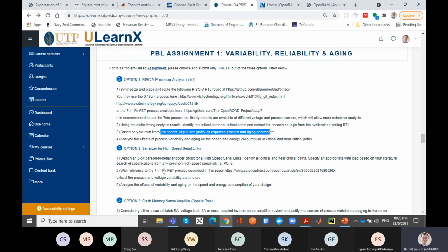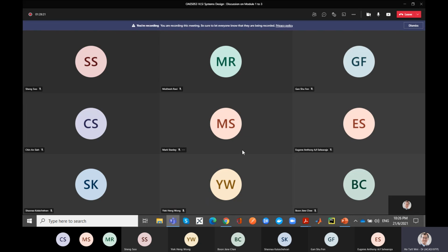After you've done your design, I actually want you to scroll through the FinFET standard cell library and identify which standard cell you are going to use. That's basically which logic gate from that family you're going to use. You can go through the index, the list of gates lah. There's a nice HTML file that you can use to see that, and you can all do this. So option 2, you can do everything by hand actually. There's nothing in option 2 that you actually need to use a software tool lah. Okay, I hope that answers the question, Eugene.